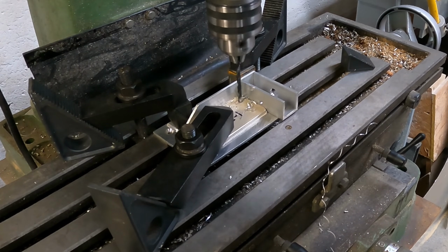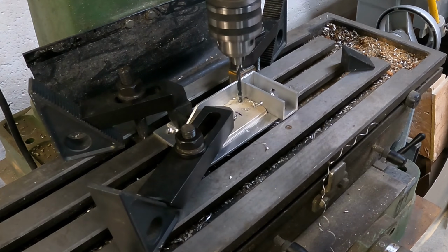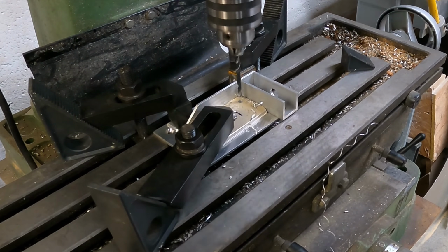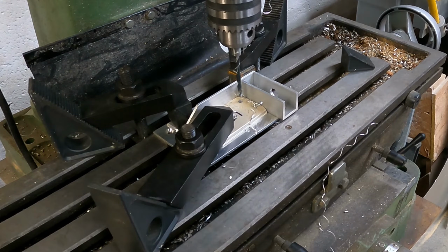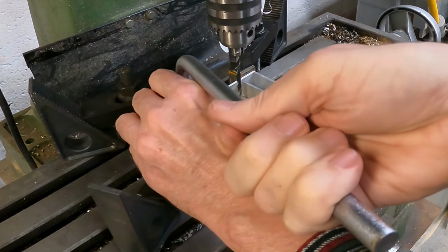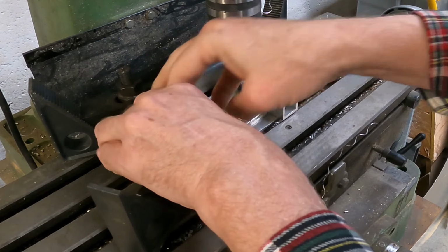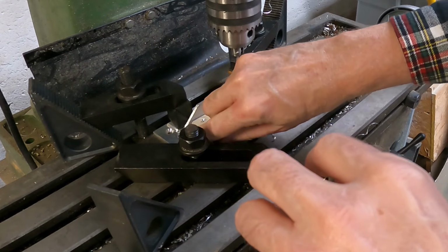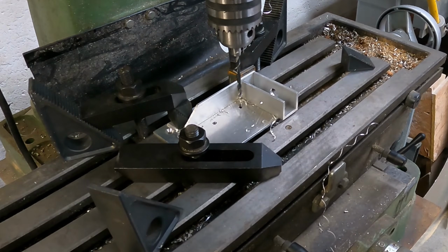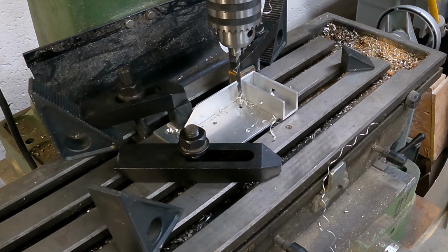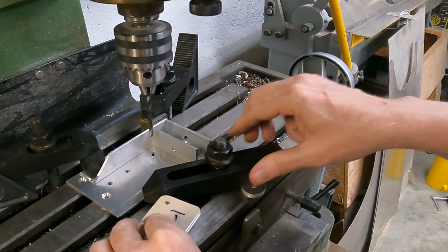But first, we're going to drill the hole that all the load spreaders have in common. So the most forward hole, the way I've designed this, is in the same spot on all these load spreaders, and that's 3/8 of an inch from the end edge and the bottom edge. So first we're going to drill all of those. Now I put a jig here on the table in order to get those spreaders in the correct position for the hole. So all I have to do is press the load spreader up into the jig and then hold it in place to drill the hole. So this is a pretty fast operation.